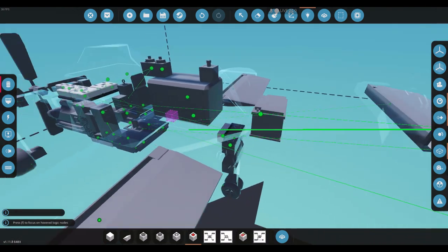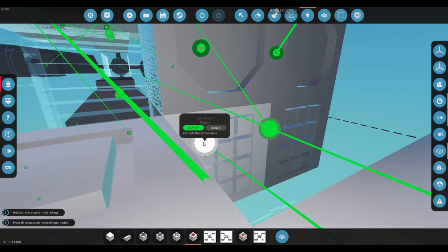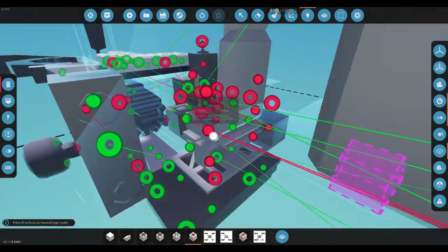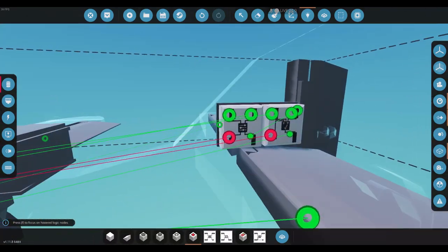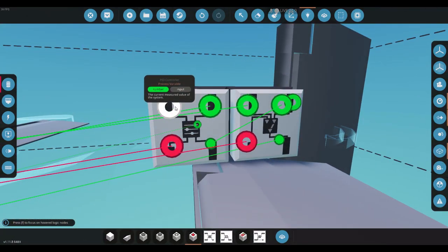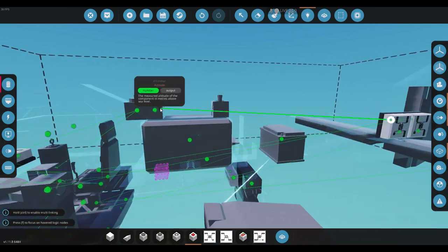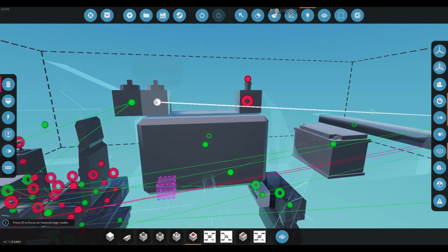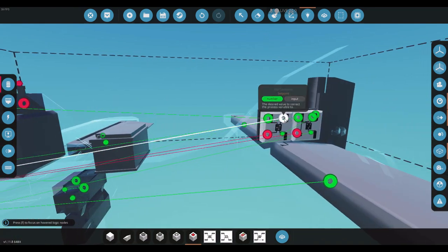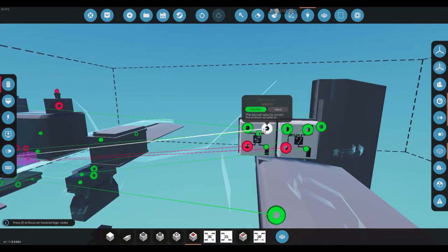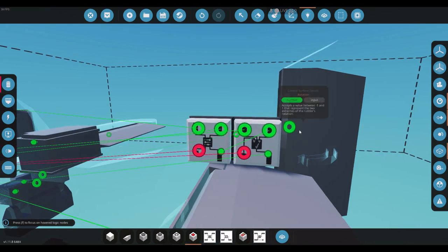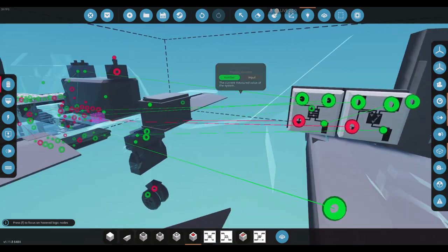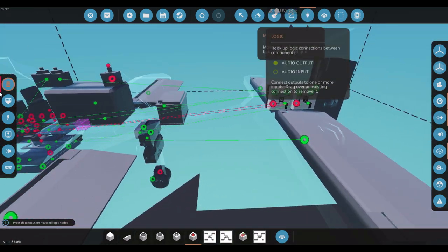For the set point, again, you're going to hook it up to your keypad input altitude hold, that's what we put up earlier. We're going to input a number to display our desired altitude, and that's what the PID will try to achieve. Now for the process variable, we hook this into the altimeter we placed a few moments ago. This altimeter is what the PID tries to correct to, or what it tries to work towards, rather. So these are hooked up. If everything's hooked up here, let's make sure there's electricity.